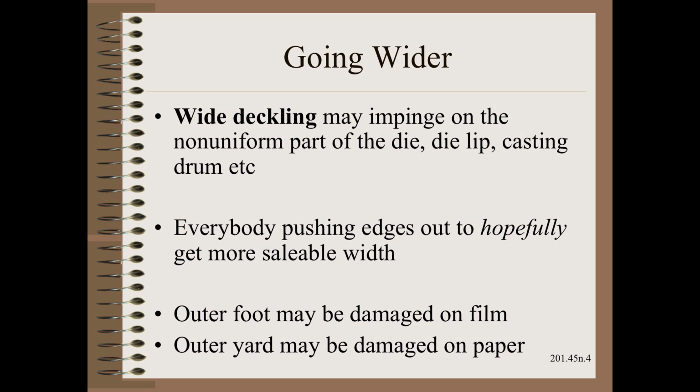In film, the edges of the die and cast roller tend to be cooler despite our best efforts. These are just two examples of the scores or hundreds of troubles found on the edges of machines. It depends on how fussy you are in defining off quality. However, in the fussiest case, you may find edge damage going in 1 foot on film and 3 feet on paper.